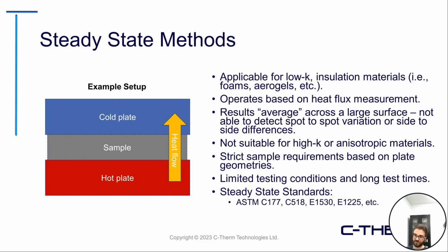How the measurement works is there's a differential applied between the two, and the sample in the middle will eventually approach what's called steady state condition, which is of course tied to the name there. But these samples do need to make really good contact with the upper and lower plate. And generally they need to be quite large. Generally speaking, you're working with samples of a standard size, having a material that's 30 centimeters by 30 centimeters